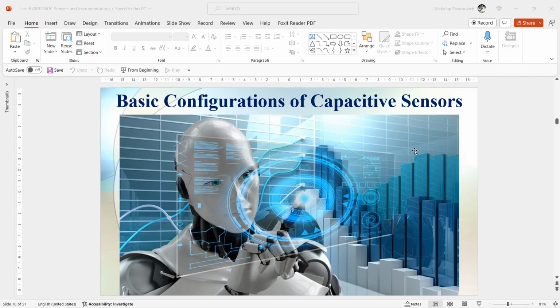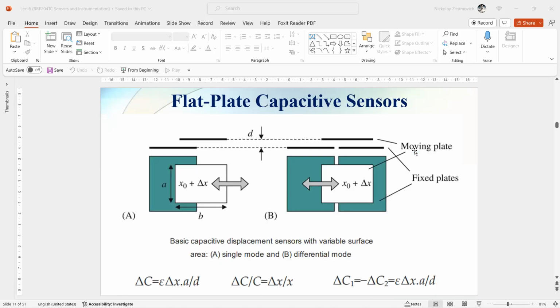Generally, electric fields are better manageable than magnetic fields because by active guarding, it is easy to create electric fields that are homogeneous over a wide area. And this is the major reason that displacement sensors based on capacitive principle have excellent linearity.